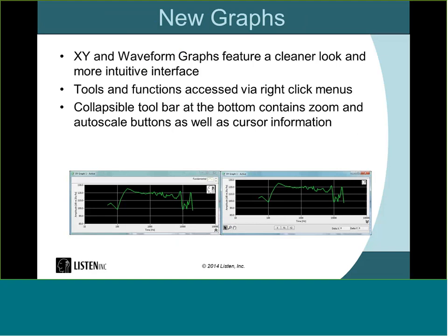Also, there's a collapsible toolbar down at the bottom. If you click the double arrows, it will actually expand that toolbar without changing the size of the window, which gives you a few extra controls, things like an auto scale button and the delta for the two cursors.